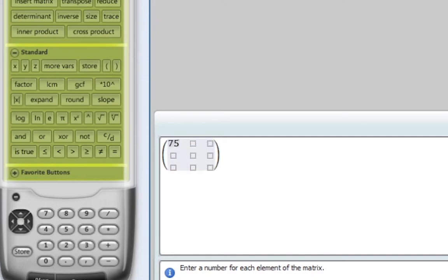In the y direction, we had positive 200, so it's a tensile stress again. In the z direction, it was a compressive stress of negative 125, so it's compressive, so it's negative. Then in the x plane, moving in the positive y direction, we have 15 MPa. That's 15 and 15. Y plane, moving in the z direction, is 10.